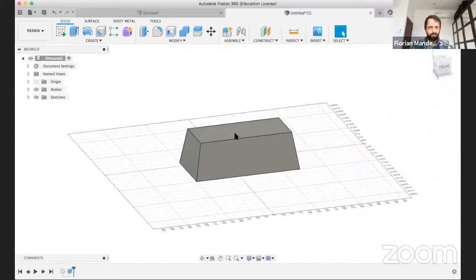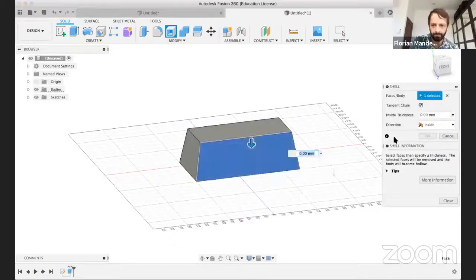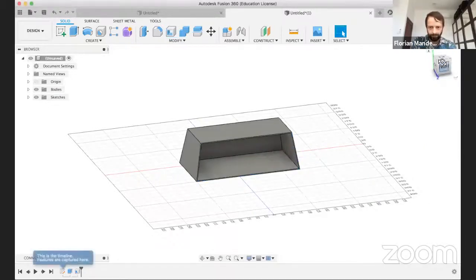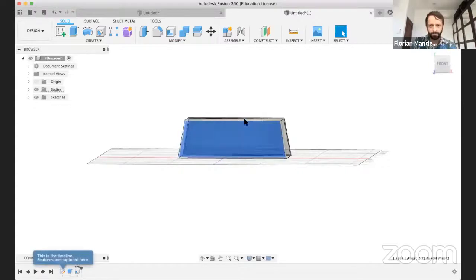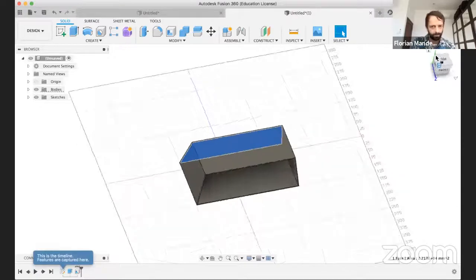Okay. And then it looks quite funny. But yeah, you have more features. So also if you want to create tools or wall thicknesses of a material, those are features here that are already built in, and make it a little bit more comfortable to use. You see how with one click I've created this cutout. Just like, okay, the shell is 2 millimeters thick, and there we go.